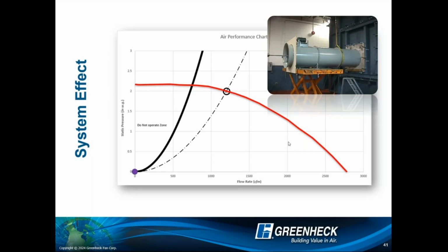And you might have mentioned this, but FEI will not matter for any fans below 1 horsepower. I did mention that. Okay, so that is important. So anything below 1 horsepower, FEI will not matter. You probably will be eventually constrained by something like watts per CFM in the future on those, but at least in terms of FEI, it won't matter.